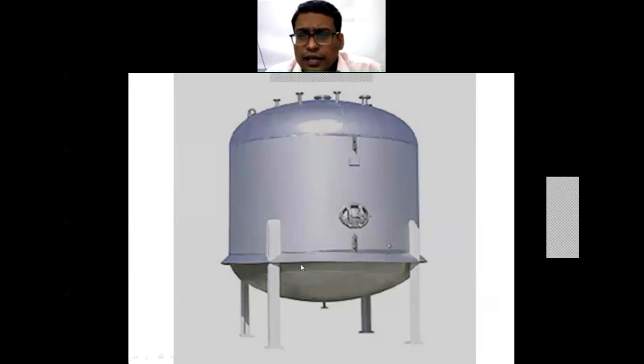Then the two heads are provided: one is your bottom head, which is elliptical, and the top head, which is also elliptical. Then a few inlets and outlets are provided for instrumentation purposes, for thermowells, for dip legs.